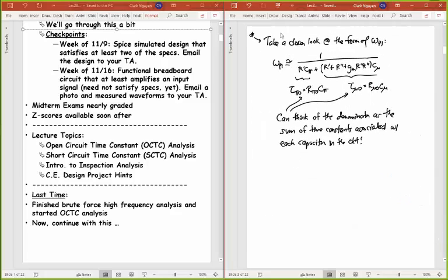And so we went and used equations and Kirchhoff's current law, Kirchhoff's voltage law, circuit analysis, and we ended up with that first pole, which is equal to omega h. And so I can be a little clearer about that. Omega h is equal to that omega p1. That's the first pole that we have.